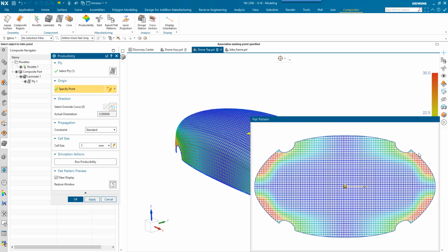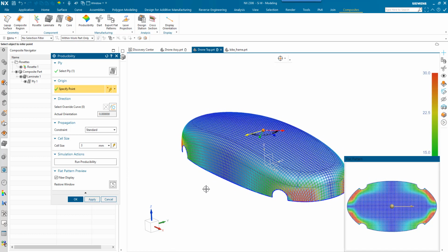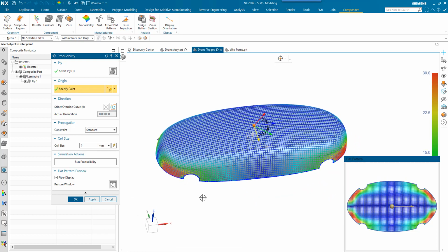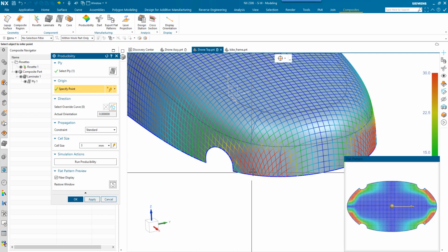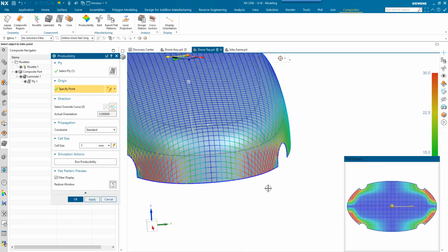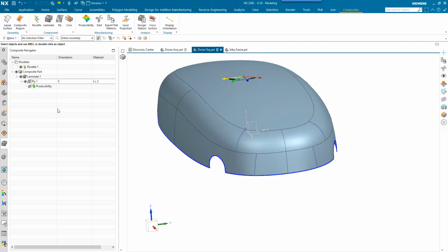And if I just make this window a bit bigger, you can see I've got a nice contiguous edge or continuous curve around the edge, but we've got these red areas, and if you think about that analogy in the Facebook post, if you saw it, of trying to get an A4 piece of paper and wrap it around a breakfast cereal bowl, you're obviously going to get wrinkling, and these areas are where the carbon fibre and these simulate the weave directions would wrinkle in the corners. So what we can do is use these curves here to create darts.